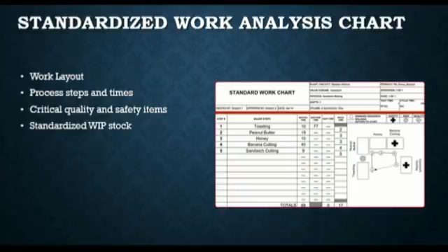The third chart is standardized work analysis chart. This chart helps to explain the layout to train workers and comprises of work layout, process steps and times, critical quality and safety items, and standardized work in process stock.